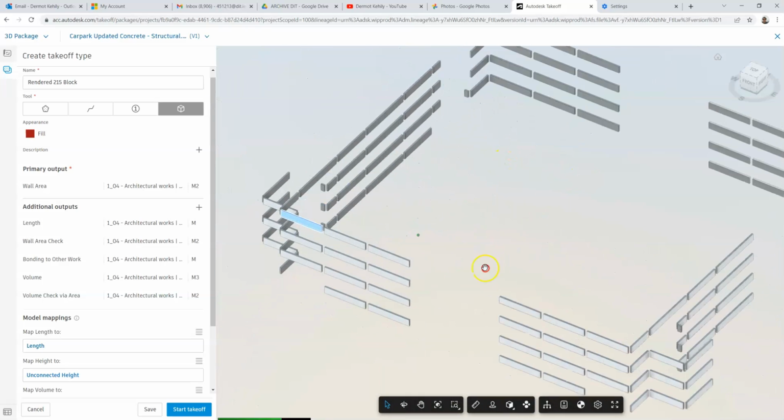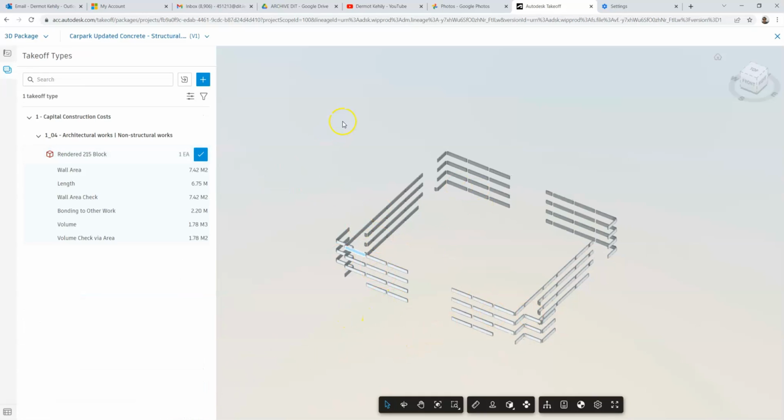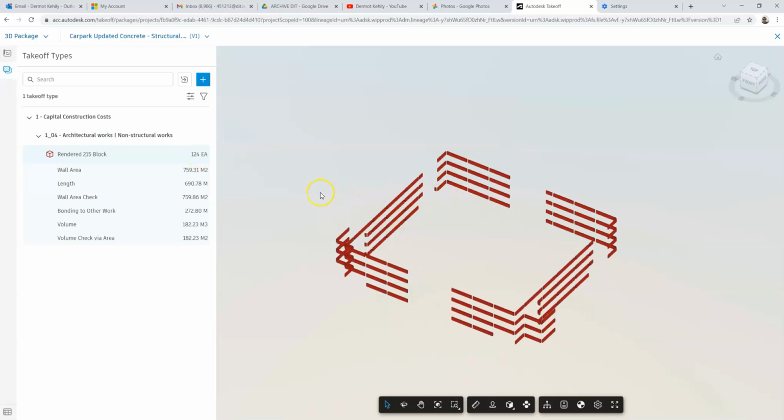So what I'm going to do, quite quickly, is get that in the center of my pane, click Start Takeoff, and highlight it by drawing a rectangle, holding down my left button as I come down to the other side in diagonal fashion, release. That's all that stuff selected. Now that's not it measured. You have to click correct. You can do them individually by selecting them. Once you do, that color changes to the color you selected in your BIM takeoff.